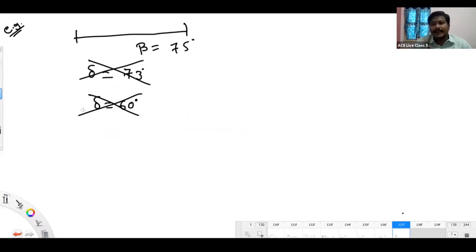Then how much do you have to maintain? See, actually, what's your aim here? We have to set our initial operating point in such a way that the system does not lose synchronism even for a small disturbance or a big disturbance.